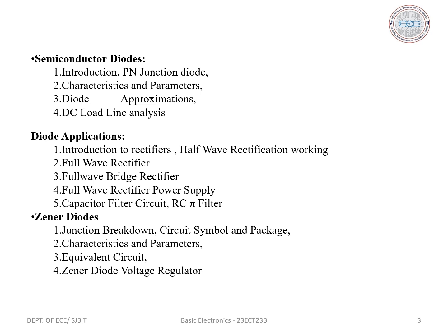The negatively charged ions on the P side will start repelling the electrons which attempt to diffuse into the P side, and after some time the diffusion will stop completely. At this point the junction is said to have attained equilibrium. The shaded region on both sides of the junction in the state of equilibrium contains only immobile ions and no free charge carriers such as electrons or holes. In other words, this region is depleted of free charge carriers. Therefore, this region is called the depletion region. This region is also known as the space charge region.